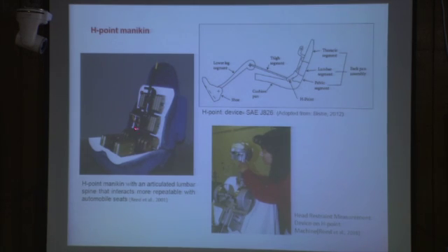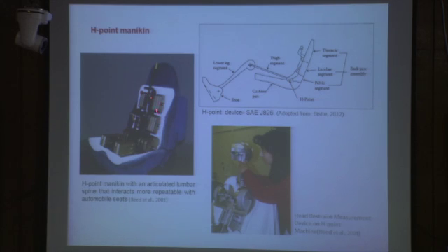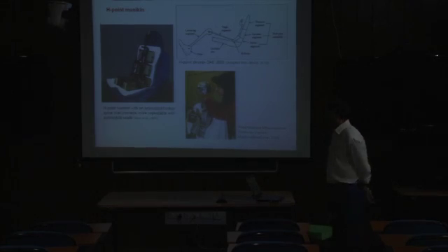While we are positioning this H point mannequin or H point device on the seat, the seat is being compressed, and on the compressed seat, this H point machine is designed in such a way that it represents the actual movement, defined body segments, and their mass. So this H point machine or H point mannequin represents a 95th percentile driver seated on the driving seat.